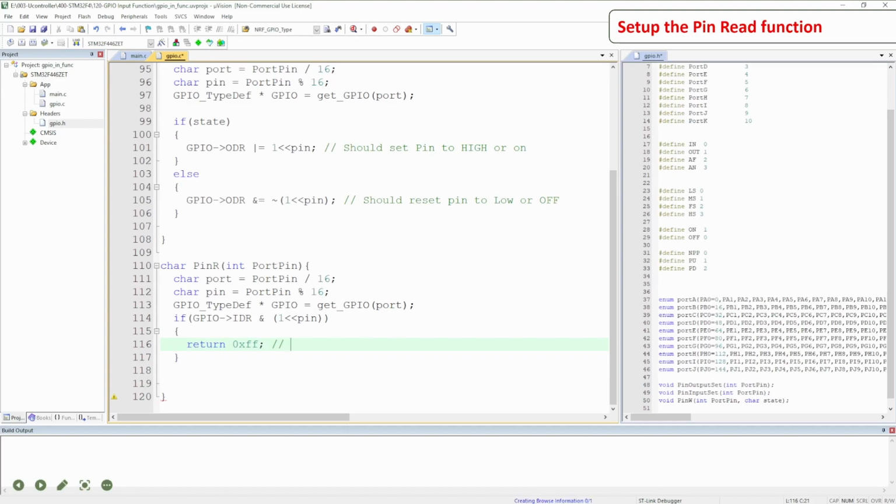And if I return 1 and I add a tilde, so let me comment it here and explain it. If I'm returning 1 and then I try to tilde it, to get the opposite of 1 for the number that we do have, which is a char, it is 0xFE. So the tilde of 1 is 0xFE, which is also kind of a logical one, and that's what I don't want. But if I put the hexadecimal FF here, the tilde of the hexadecimal FF is a 0. So that's why I'm putting this one like this.